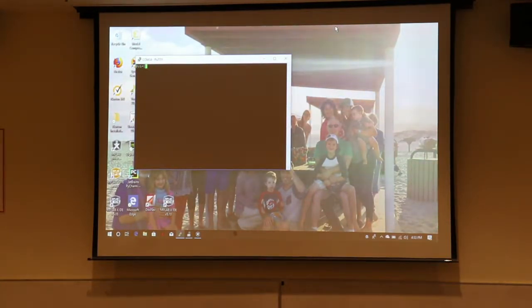So that's a perfect example of several things going on at the same time, and sometimes along with that I might use one of the other colors of the LED to blink every now and then to tell me if things are working, and I can use that to help debug the code, and I can also obviously single step through it. What's interesting is the PWM module takes care of writing that recurring signal out to the PWM port.